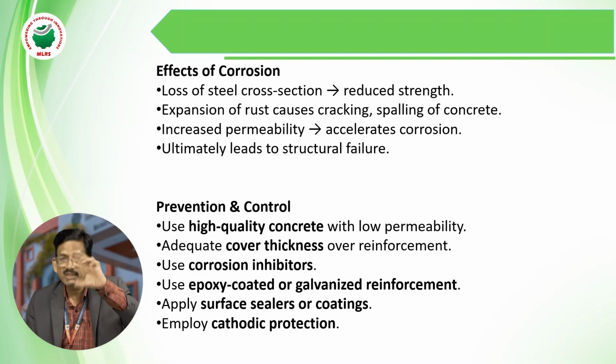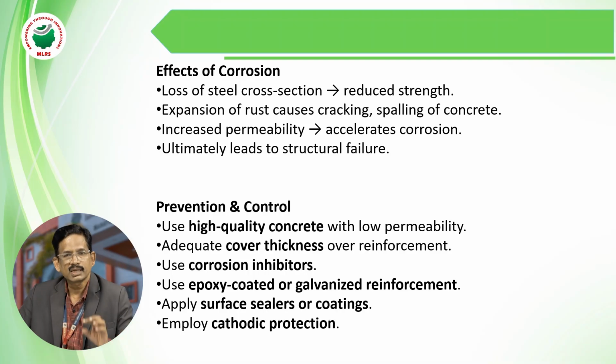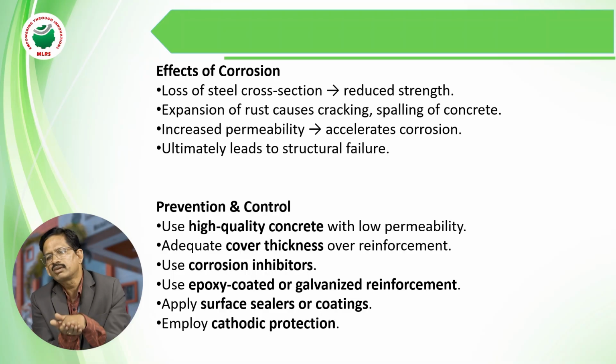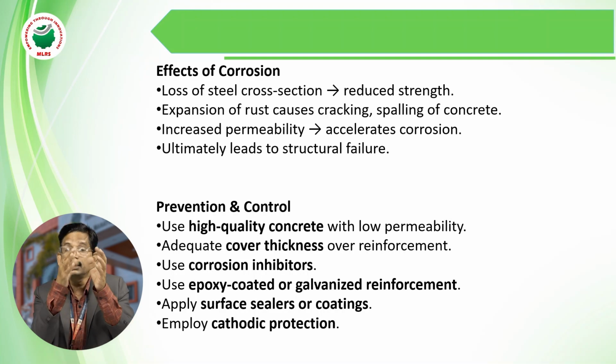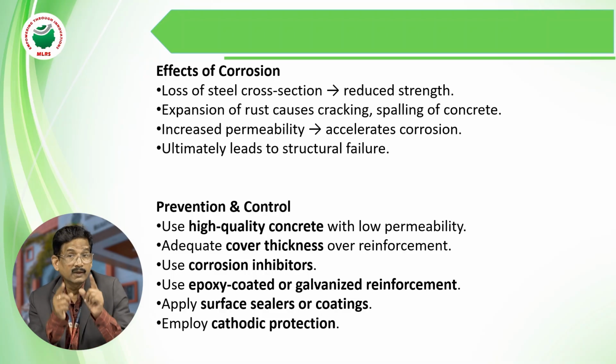And adequate cover thickness. I already told you, cover is also very, very important. In columns, we use 40 mm. In footings, we use 50 mm. In beams, we use 25 mm. In slabs also, 15 mm. Why? The cover is required for placing the concrete. Otherwise, if you do not provide the cover, how will the concrete be placed above the steel reinforcement? That's why failure of the cover is also one of the reasons for corrosion of the reinforcement.